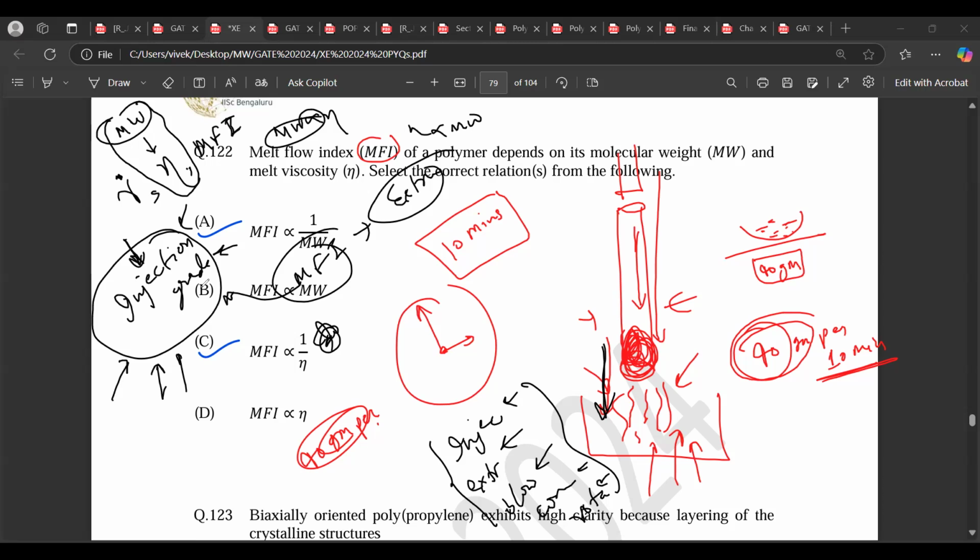Why do you think in injection you have this? This is the order of what? Anyone who has learned my notes? Shear rate. What is this order? Shear rate. Increasing shear rate. Yes, shear rate or strain rate, right? So where do you need high shear? Come on, guys. Injection molding. Where do you need the highest shear rate?